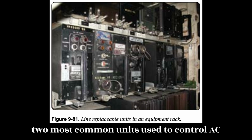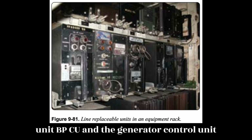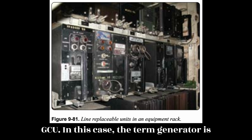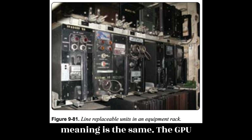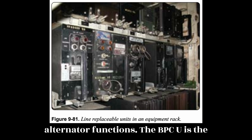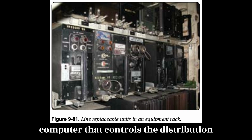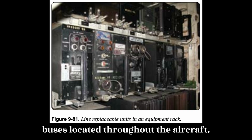The two most common units used to control AC alternators are the Bus Power Control Unit, BPCU, and the Generator Control Unit, GCU. In this case, the term generator is used, and not alternator, although the meaning is the same. The GCU is the main computer that controls alternator functions. The BPCU is the computer that controls the distribution of AC power to the power distribution buses located throughout the